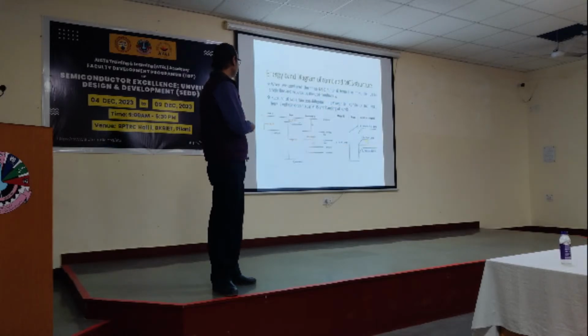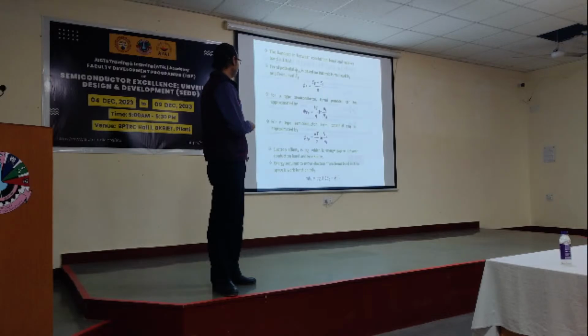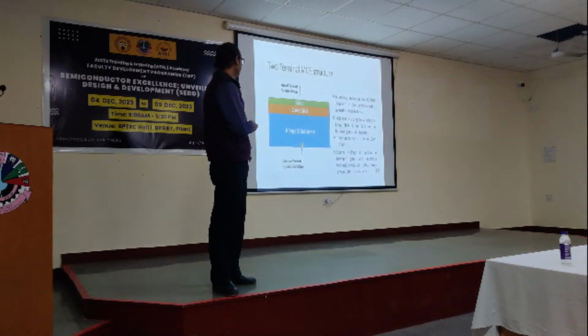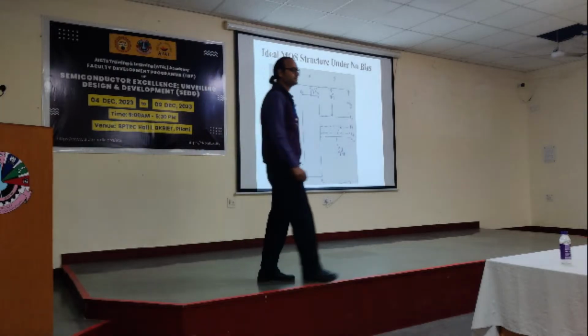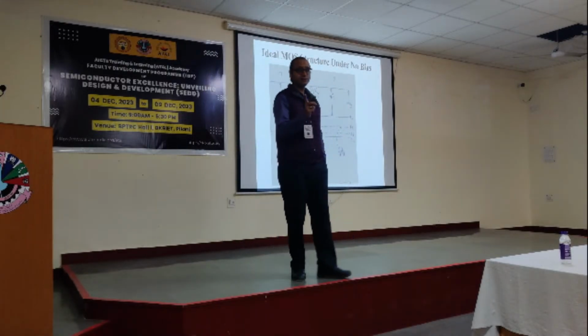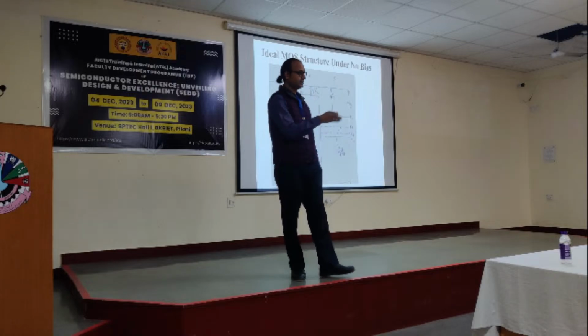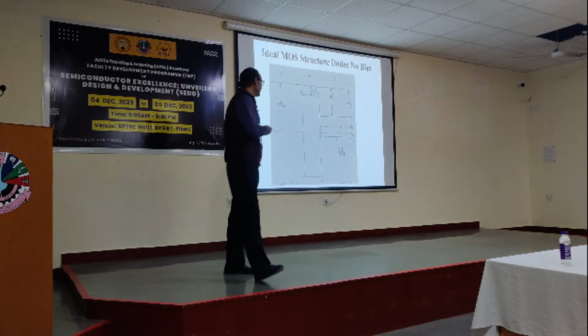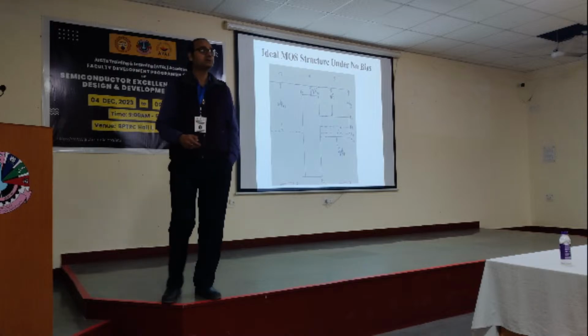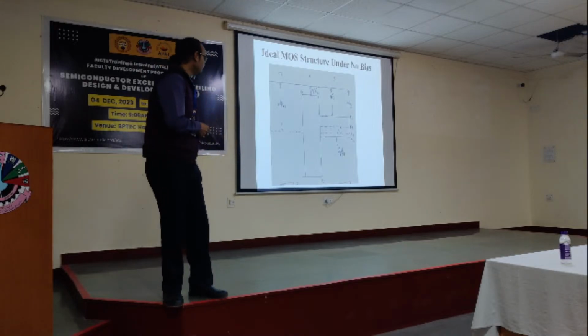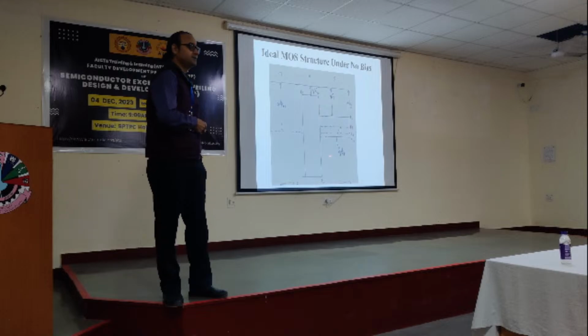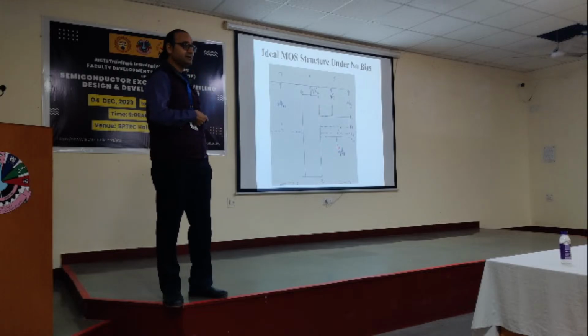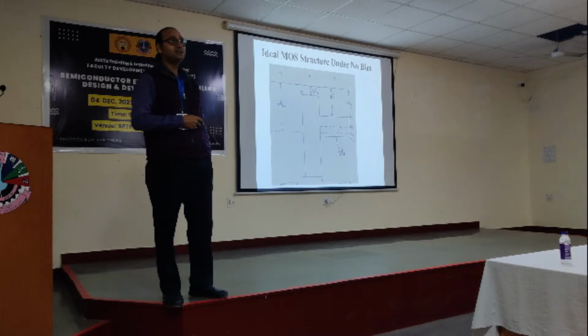Should I switch to another where I had that? Yes, suppose this is the situation, right? Phi m equal to phi s. Now at this point for flat band, zero voltage is required at the gate. Is that okay? My question is, suppose this oxide is not an ideal one now. It has positive charges, say. So in order to invert this channel, this is p type, na? Invert means I want to make it n type. What will happen to that voltage?